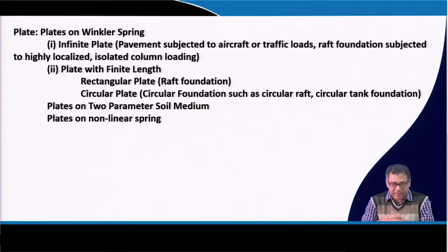The plate can be an infinite plate, that means pavement subjected to aircraft or traffic loads, or an infinite raft foundation subject to highly localized load. That means if in a raft foundation the loads are concentrated on a particular zone, then that can be idealized by an infinite plate. Then pavement can also be idealized by an infinite plate.